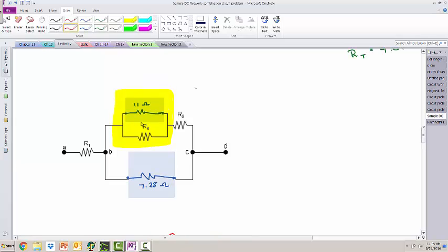Why do I care about that? Because if I go up here, that equivalent resistance was for this yellow boxed in area. So the voltage drop for this yellow boxed in area, so we call this point to this point, is equal to 9.46 volts. But since it's a parallel branch, that means that the voltage drop from right here to right here is 9.46 volts. And while the electrons have a choice which direction they go, the voltage that they start out with is the same as the voltage they end up with, no matter which way they go. So I can find out how many electrons go marching through R4 by using this information. And I'm going to go ahead and do that.